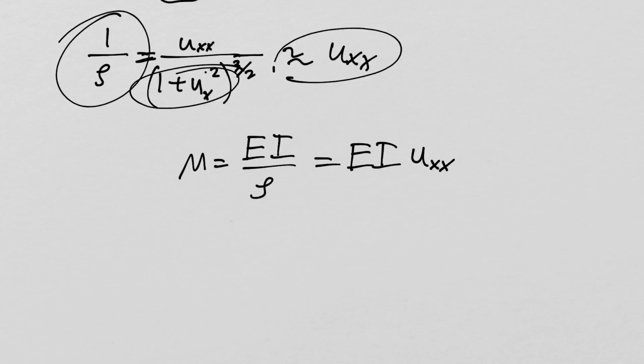And that is actually a really important expression that takes our internal forces and tells us something about them given the shape of our final formula. Given our final formula, we can learn about the internal moments through this expression. And the cross-section, the dA, is built into that. The material properties come in through the Young's modulus, and the physics comes in through the moment.